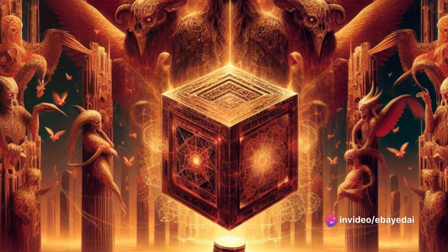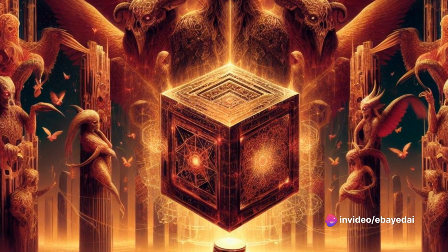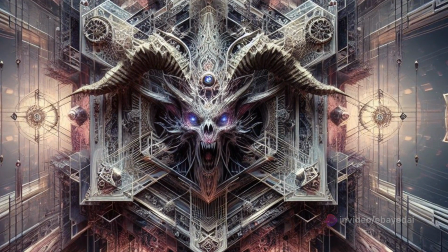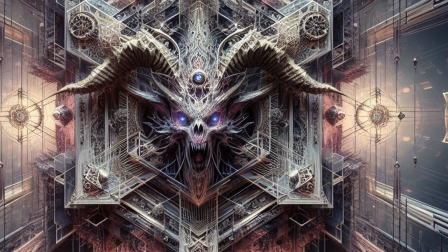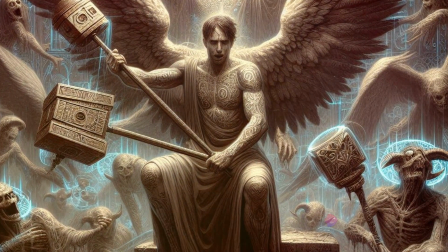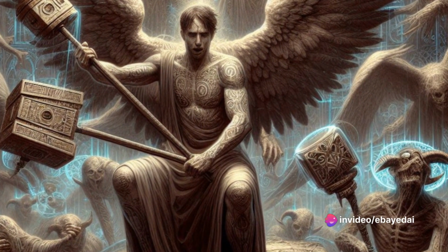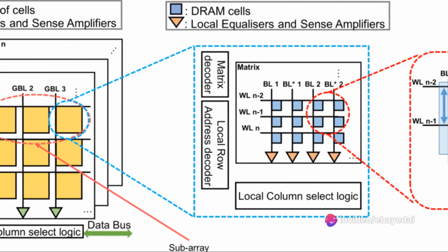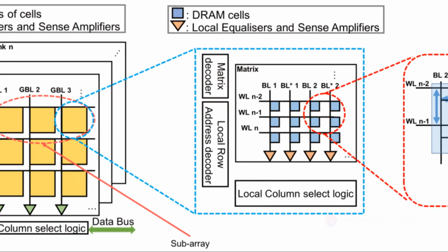Consequently, read operations are of a destructive nature because the design of DRAM requires memory cells to be rewritten after their values have been read by transferring the cell charges into the row buffer. Write operations decode the addresses in a similar way, but as a result of the design, entire rows must be rewritten for the value of a single bit to be changed.